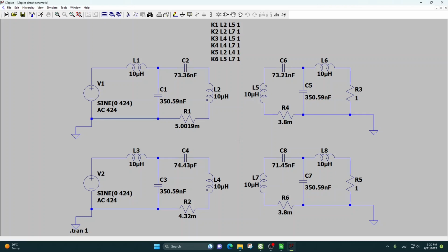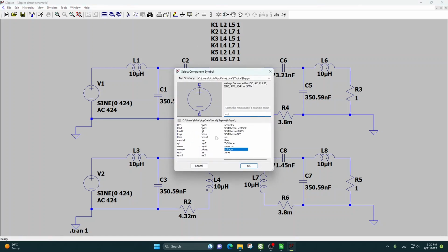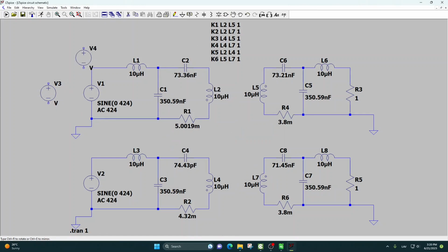When you prepare an LTspice file for integration with CENOS, there are a couple of things to keep in mind. First of all, within the file, a voltage source with a sinusoidal waveform needs to be defined. If by default you add a voltage component, it will look like this, and if you right click on it, you can simply input the DC value of the voltage.